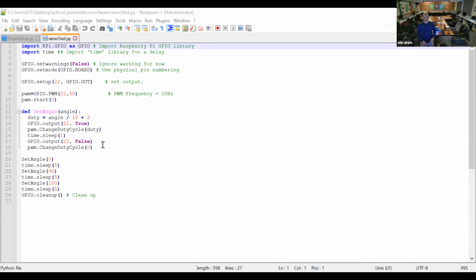So the first thing is we need to import the GPIO libraries. We're in Python, and we need to import the GPIO registers. I can make it bigger for you. This is why we have the first line here, which imports the GPIO registers. The second line is we need to get the time module in. The time module basically enables us to put delays in there, like for example, we need to sleep for 10 seconds or wait 10 seconds. So we need to do that.